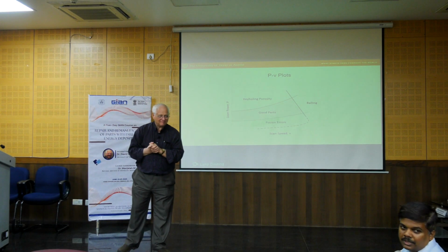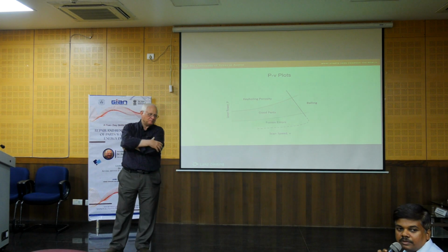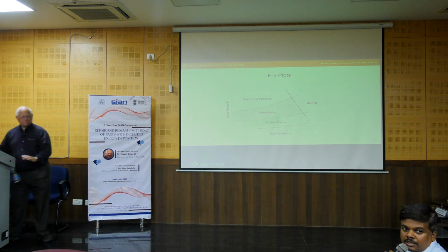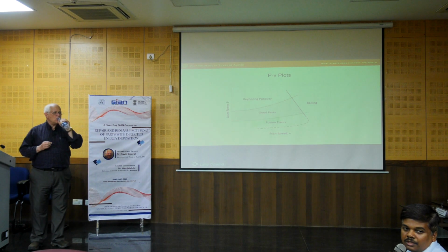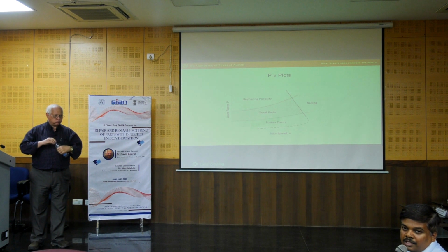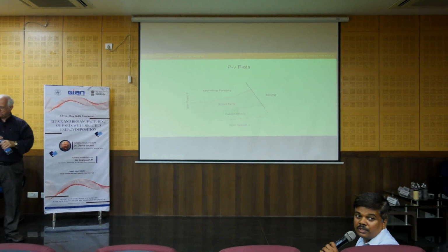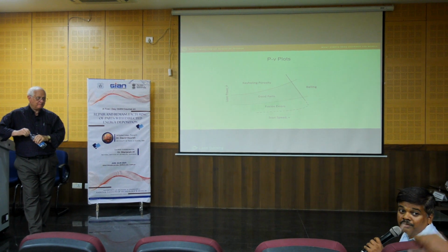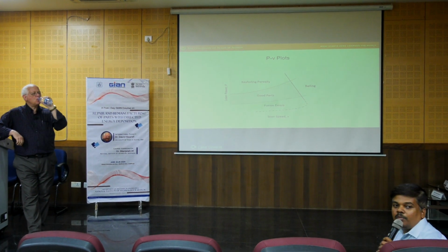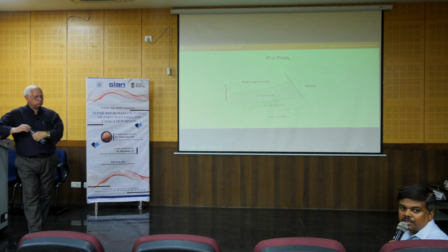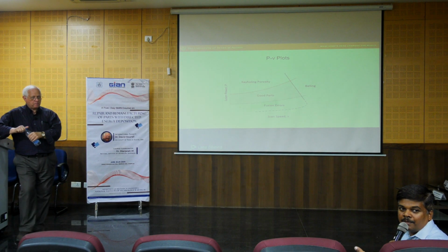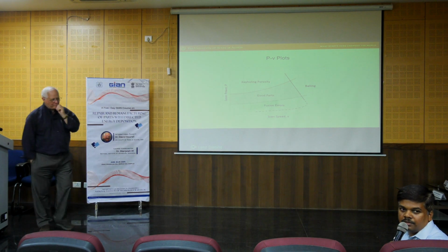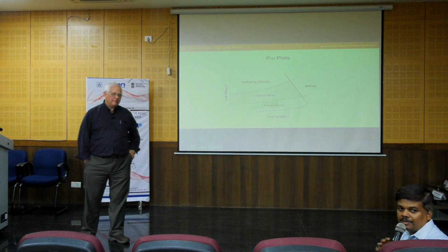Yeah, along with that, you can do a lot of numerical work with respect to the powder flow, how the powder is interacting with the laser. That's one of the major challenging issues in laser DED. As well as the melt pool, and how your cooling rate is going to affect the part. And topology optimization: that application is completely in design, but when considering topology optimization, the result can be manufactured by the DED process. Yes, definitely, we can do that. Yeah, thank you.